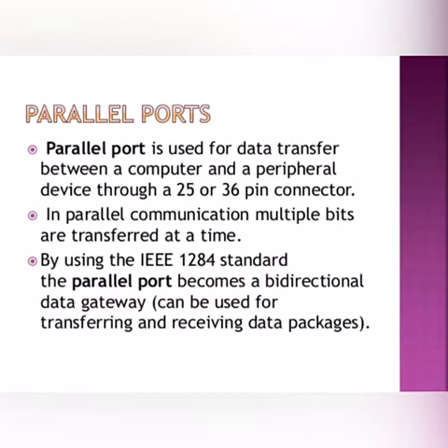Now let's start discussing the first type of port, that is parallel port. Parallel port is used for data transfer between a computer and peripheral devices through a 25 or 36 pin connector. In parallel communication, multiple bits are transferred at a time. By using the IEEE 1284 standard, the parallel port becomes a bidirectional data gateway. Here IEEE stands for Institute of Electrical and Electronics Engineers. It can be used for transferring and receiving data packages.